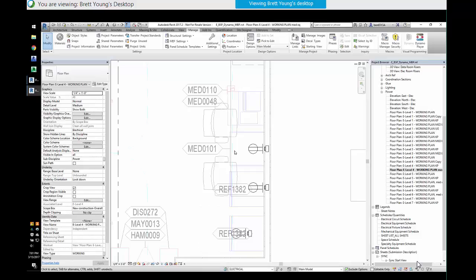We'll give it the load, we'll give it the location. Revit helps with the location. The load might be in some unique Excel file, but if we're talking about the same key value, connected to the location of the receptacle. Yep. And I know the default is 156 inches. Yeah. The receptacle. So that might be another issue, another solution to read the information and place the right elevation. You don't have to worry about the elevation and the power you need to provide, and then you go to each receptacle and modify the instance parameters. Right. Like one by one.